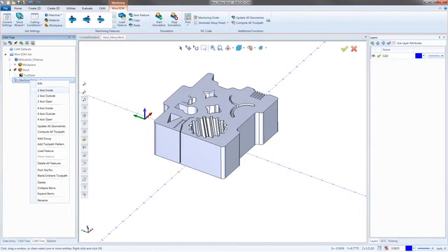So when you're doing an inside, yeah, you're cutting it out, you're making the die. And so when you're doing an outside, you're cutting the punch for it, something like that. And then the 2-axis open, like I said, that should be able to do just about everything. But primarily it's for shapes that aren't closed. So you've got your inside and outside, those should always be closed shapes. And then the open, which would be an open shape. And then you have your 4-axis inside, outside, and open.